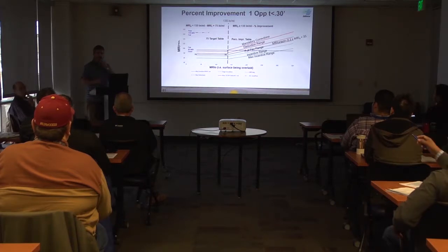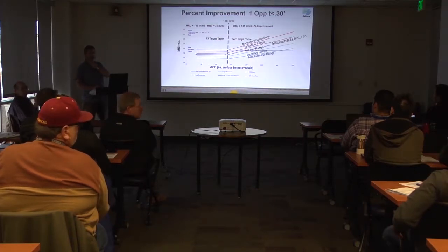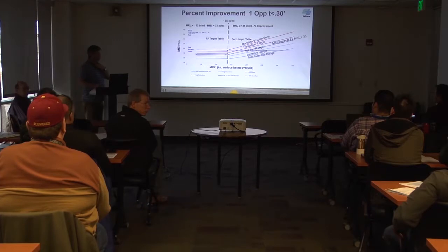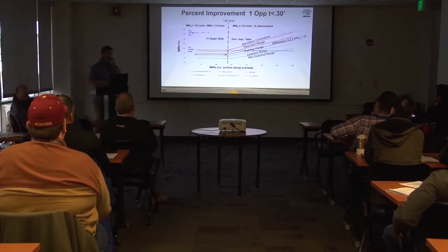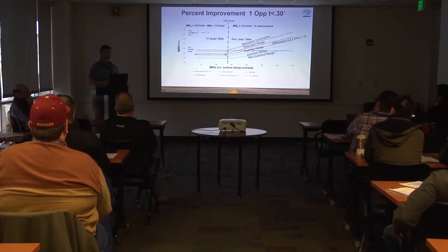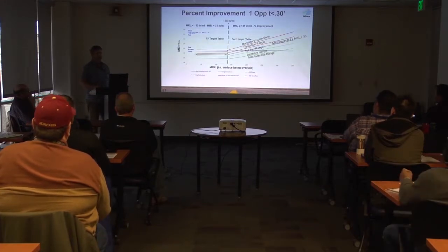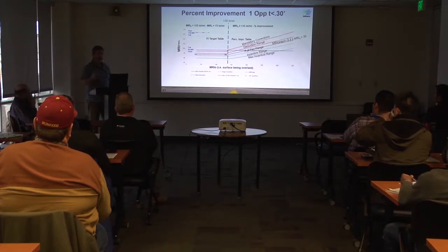Are there any questions on this yet? If cold planing is involved, is that considered an opportunity also? The question is, if cold planing is involved, is that an opportunity or not? That depends. The way the specs read, if you can cold plane in one shift and pave in a different shift, that's an opportunity.